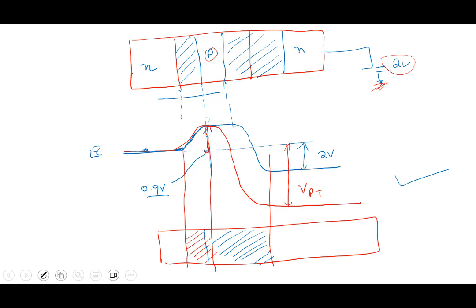So what begins to happen is that when it takes away charge from here, it has less charge left, and the other one gets more charge. So it begins to look like this. Less charge on this side means less voltage drop. And then it begins to go like this here. What has happened? Do you see something that has happened? The barrier height from here to here has become less, which in effect means it is as if the junction is getting forward bias. How do you reduce the barrier? So now the electrons have an easier time going in here. You apply even more, and it will become like this here.